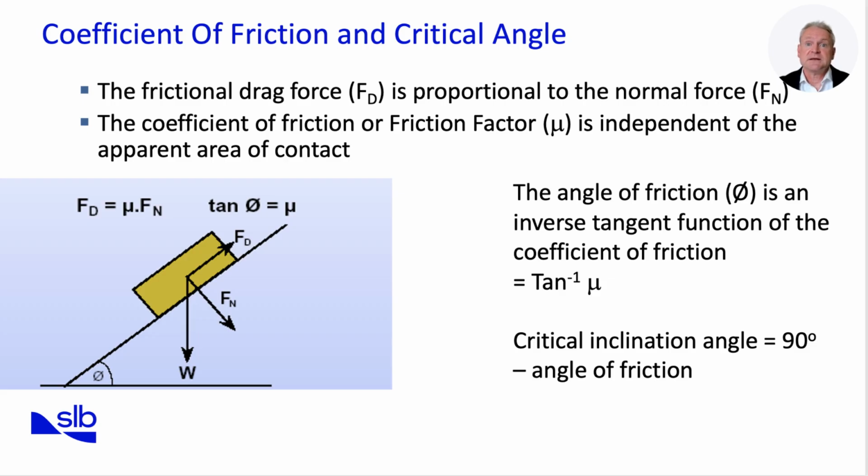The diagram illustrates how frictional forces act on the string during axial movement. When picking up, friction adds to the apparent hook load, whereas during slack off, friction reduces the measured hook load. Both are direct outcomes of the normal force and the coefficient of friction. This behavior is symmetrical. Friction always opposes motion, whether upward or downward. From an operational perspective, recognizing these trends allows us to differentiate between expected drag and abnormal increases in hook load, which might indicate tight spots, cuttings accumulation, or other downhole restrictions.